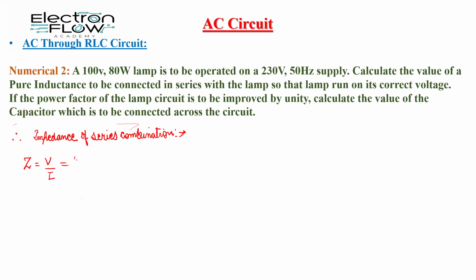The voltage is 230 and the current we have calculated is 0.8, so the value of the impedance is equal to 287.5 ohm.